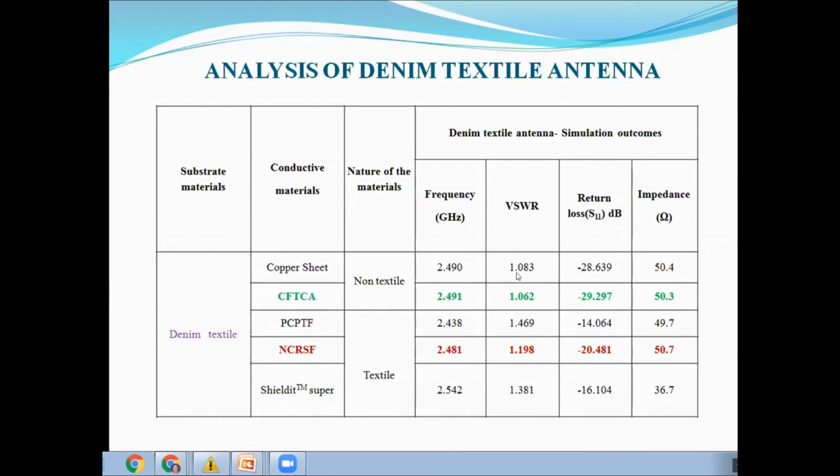And the return loss is less than minus 14 dB for all of them, so minus 28, minus 29 like that. And the impedance is approaching the characteristic impedance of 50 ohms for all of them. The last one is not suitable, at 36.7.